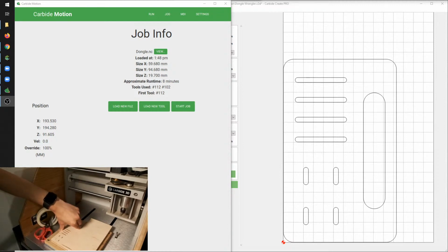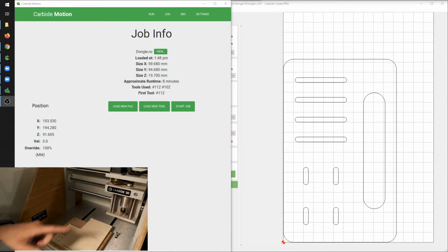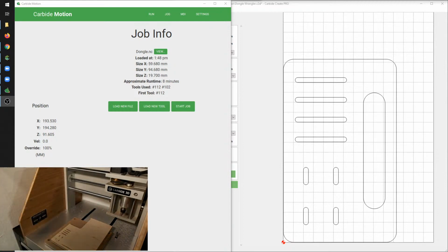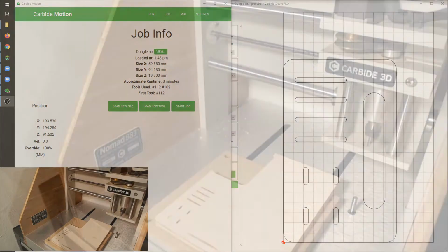Honestly, it just needs to be good enough, because the cuts that the 1/8" end mill will make are completely independent of the SSD slot here and the final cutout. That seems more solid. I don't really want to push it, but fingers crossed, I think it'll hold. So let's swap that out to an 1/8" end mill, and we'll make the new toolpath. I should probably have switched to the full camera feed, so let's do that.